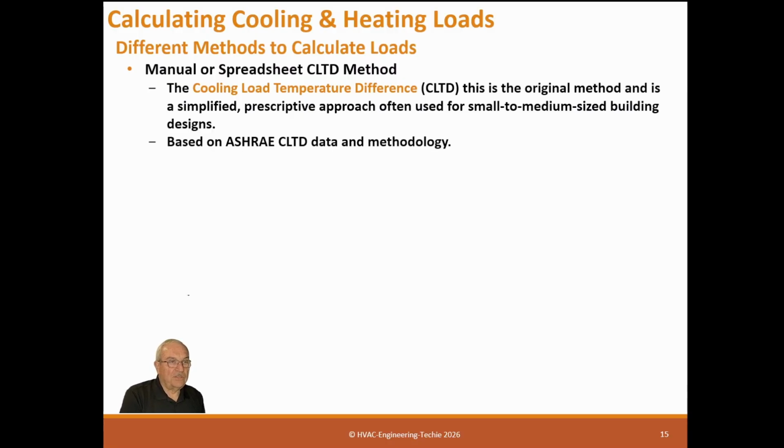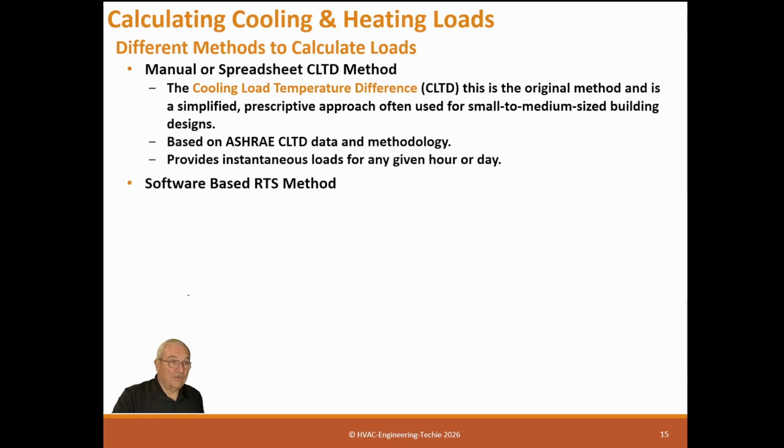Based on ASHRAE CLTD data and methodology, it's available in the Handbook of Fundamentals and provides instantaneous loads for any given hour or day for cooling or heating. So you can select the hour you want and do just that hour, making sure the occupancy is there and making sure the weather data meets that hour. You can do that. So basically, this is a system to use for peak loads. You're not going to use this method to do any average loads or energy calculations. That's not going to work.